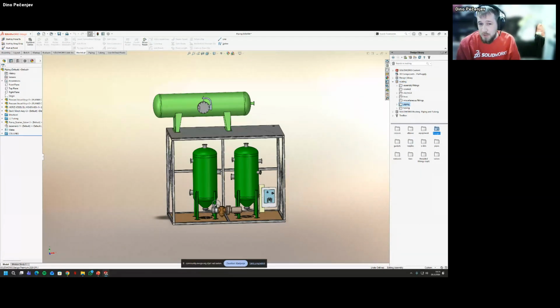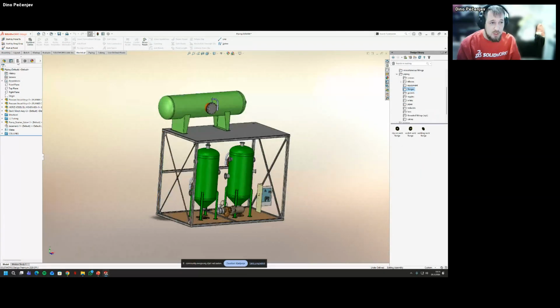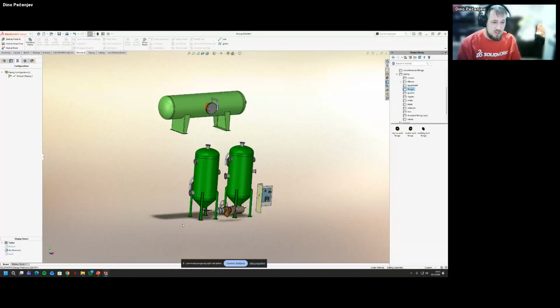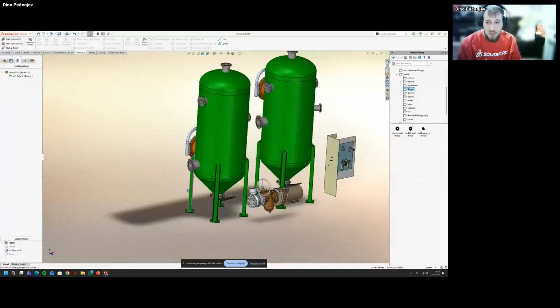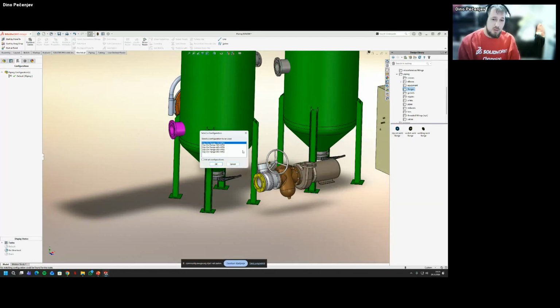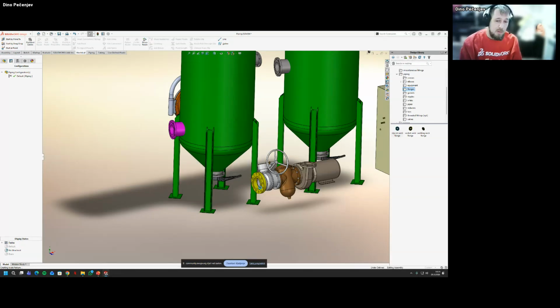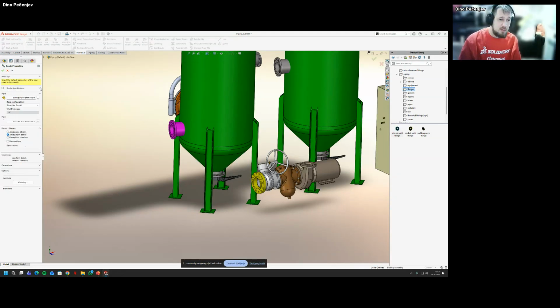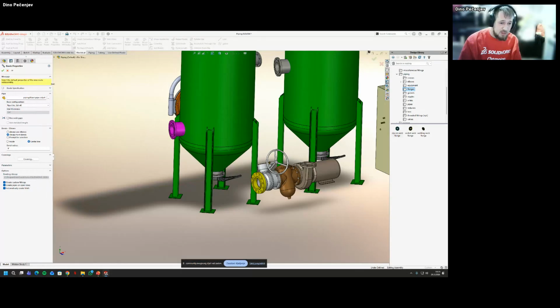So we're going with the piping. We're not going to do anything special here. I'm going to use display state, not structural. And for the flange, I'm just going to drag and drop one. This uses mate references, so I'm going to use slip-on flange. If any configuration is not listed here, I can always use the checkbox list all configurations, just for a notice. So I've set my first flange. I'm getting my information, but I'm using the default template I've set.